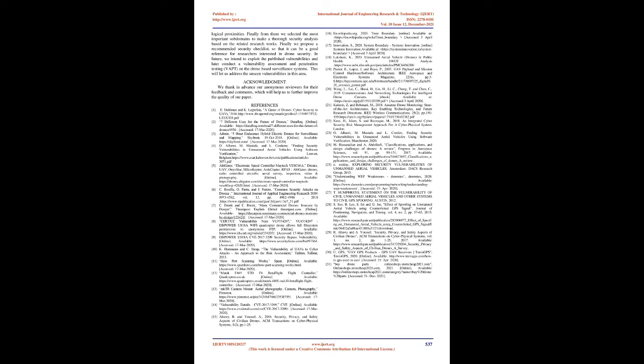Subdomain: flight controller. Vulnerable to Trojans, hardware plus software. Vulnerable to injection of malicious data into sensors. Subdomain: GPS module. GPS spoofing attacks: original GPS satellite signals are overlaid by spoofed GPS signals, as GPS signals are easy to spoof because they are not encrypted. GPS jamming attacks: the attacker produces signals in GPS jamming that conflict with the GPS signals, causing the GPS receiver in the UAV to malfunction.